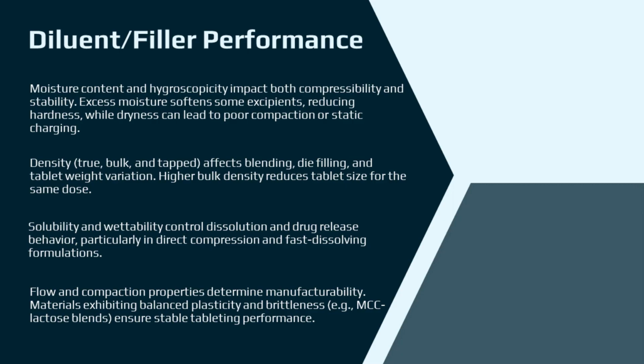In formulation science, a diluent's performance depends not only on its chemistry, but also on how it interacts with moisture, density, and mechanical behavior during processing. A controlled level of moisture can enhance compressibility, but excess leads to soft tablets and sticking, while dryness causes static and poor bonding. Density influences die filling and tablet size. High-density powders improve dose efficiency, whereas low-density ones aid disintegration but may cause flow issues. Solubility and wettability govern dissolution, especially in direct compression systems, where poor wetting can limit drug release.